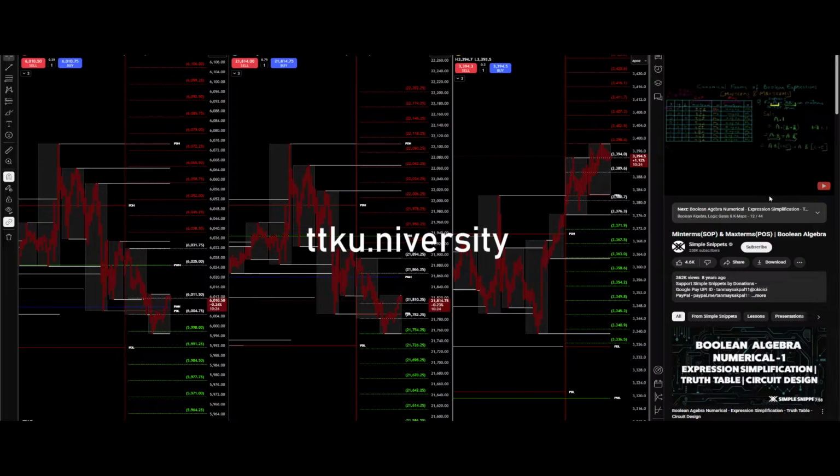Now I'll write the answer over here. Okay, so we expanded this single variable term into this entire expression. Now we just need to substitute it at this place. So the final function would be this entire value plus ABC. Now notice that we have ABC 2 times, so we can ignore one. Okay, so we've got our answer, and the answer is ABC or ABC complement, or AB complement C, or AB complement C complement. Now we need to represent this in sum of product or min terms form.